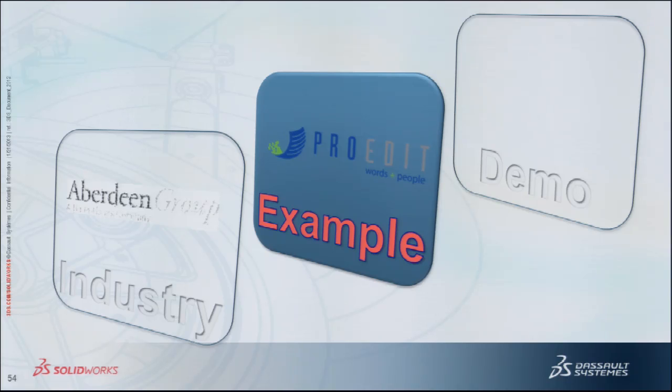What you could do is, there's two different ways. If you're receiving the SolidWorks model, then yes, you would need the corresponding toolbox features if they're custom, or alternatively, they could use the Composer add-in on their end and save out the Composer file directly and then send that to you. So there's different ways of working with it. If they do it the second way, then the Composer model would come, and the toolbox data, the graphics data would come across directly.